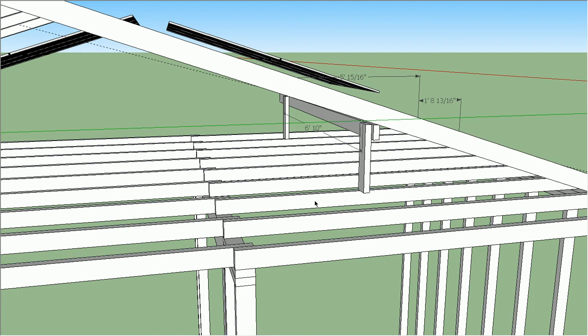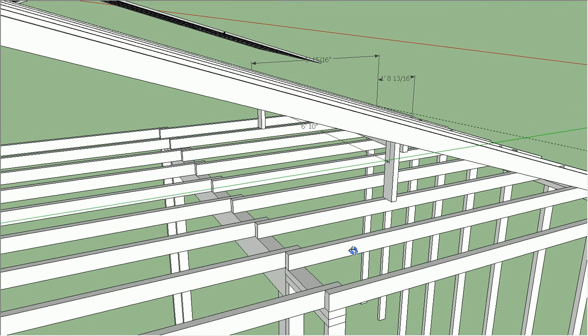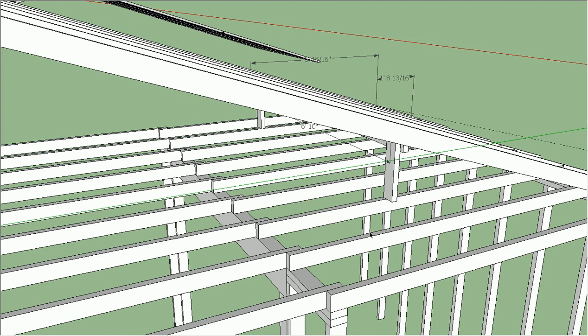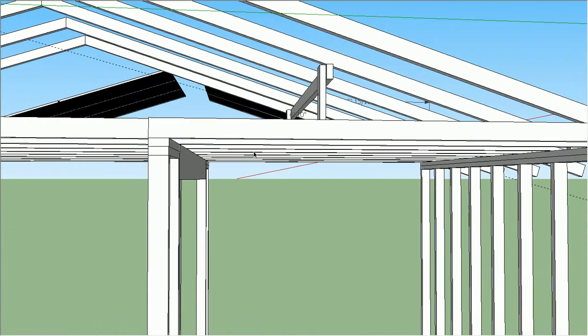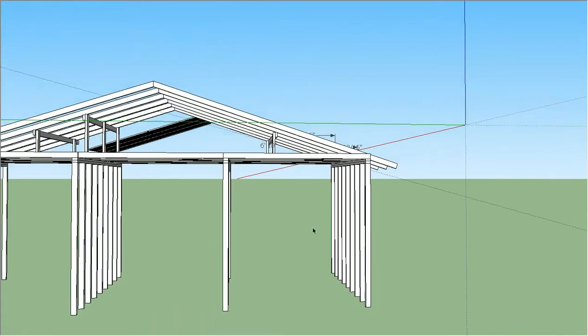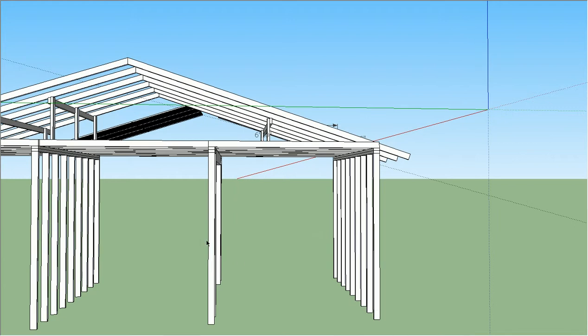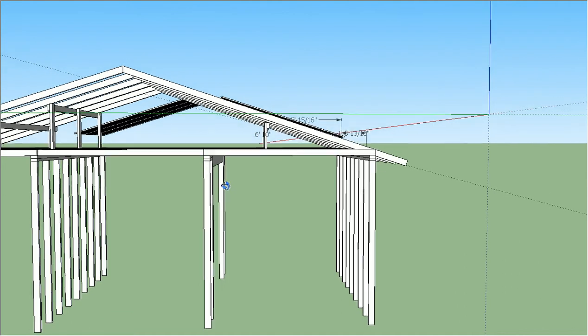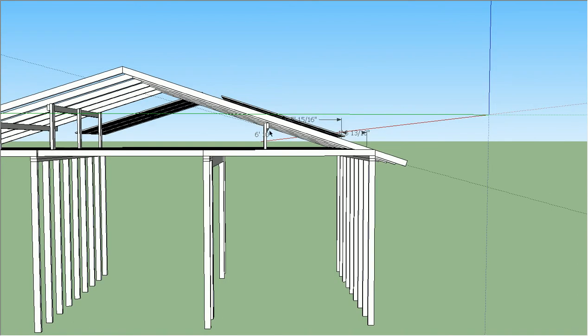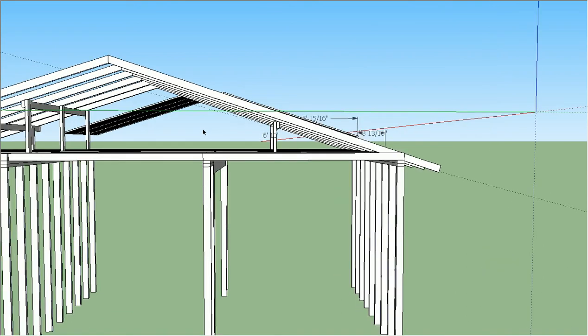So the ceiling joist is also, we haven't made it to the wall yet with our load, so you want to record the size, 2x4 in this case. The spacing, I put these ones at 16 inches on center, and the span. Now the span is why we'll frequently ask you for the dimension between the exterior wall and the next interior wall, because that dimension will define the span of these ceiling joists. And when these ceiling joists are getting all the extra load from the strut, it becomes very important.